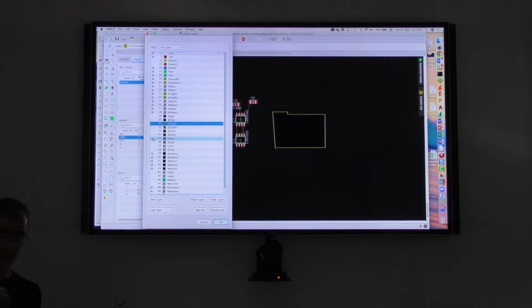And you have to solder on both sides, for example, but because you have components on both sides, then the components must be fixed on the board. Otherwise, you turn it around, it drops off, so it doesn't make sense. Then you have 2 or in most cases 3 points where you have glue, then you put it on the board, it's glued on the board, and then you can go on with the process. So there's a lot of stuff to think of.